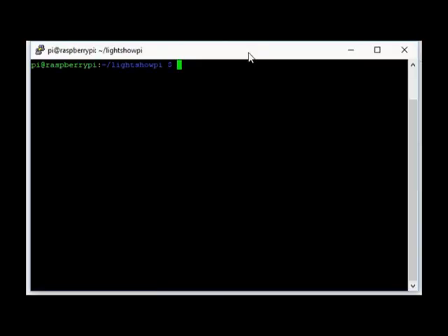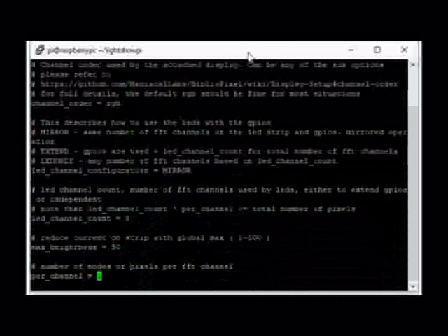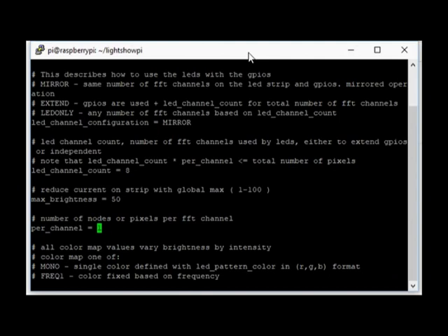Okay, now time to edit our config file for sACN. And since overrides is still pointing to this file, we can use it. Change this to sACN. It's still a strip. This is ignored. This is ignored. We're going to change this because we set pixel count to be 288. We want 8 times 36 equals 288. Now, if in the ESPixelStick configuration you set the pixel count to something lower, then you can do that. If we don't do this, then some strange things will happen on the strip, but that's about it.